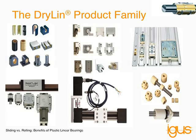Here's an overall comprehensive look at the Dryland product family by Igus. So this is our linear bearing specialty line. Starting from the top left, you'll notice a series of round parts. Those are interchangeable with recirculating ball bearings. We also offer aluminum shafting, steel shafting, and stainless shafting, both inch and metric sized. Below that, you'll see Dryland T, which is interchangeable with common profile rails that are on the market, but again uses plastic sliding parts instead of ball bearings.